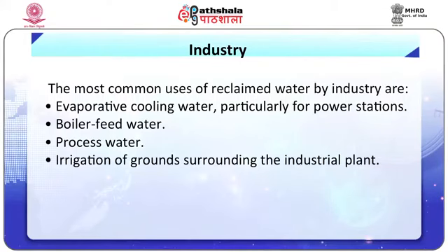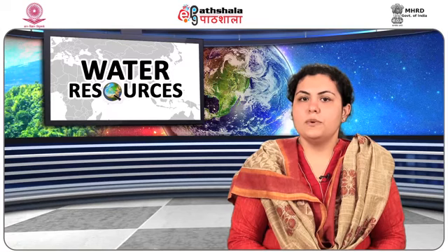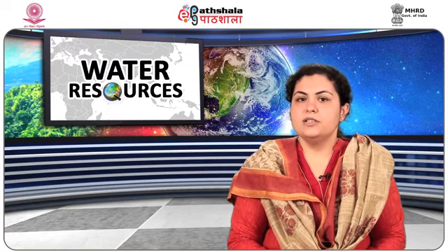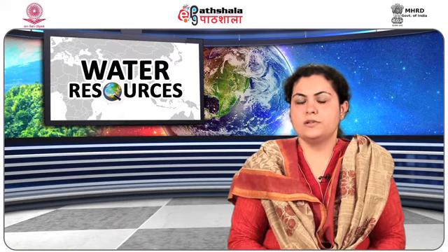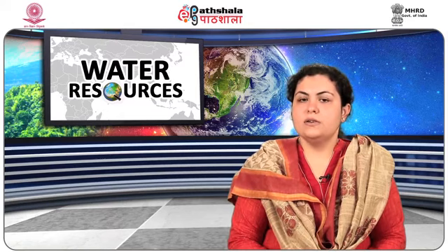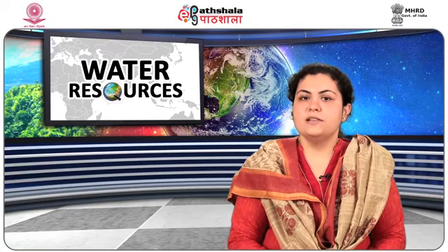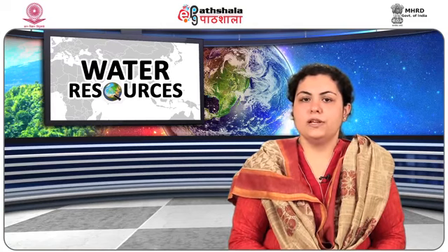Industry. The most common uses of reclaimed water by industry are evaporative cooling water, particularly for power stations, boiler feed water, process water, and irrigation of ground surrounding the industrial plant. The use of reclaimed wastewater by industry is a potentially large market. Industrial reuse of water is cost effective for industries where potable quality of water is not required, and where industries are located near urban centers where secondary effluent is readily available for reuse.